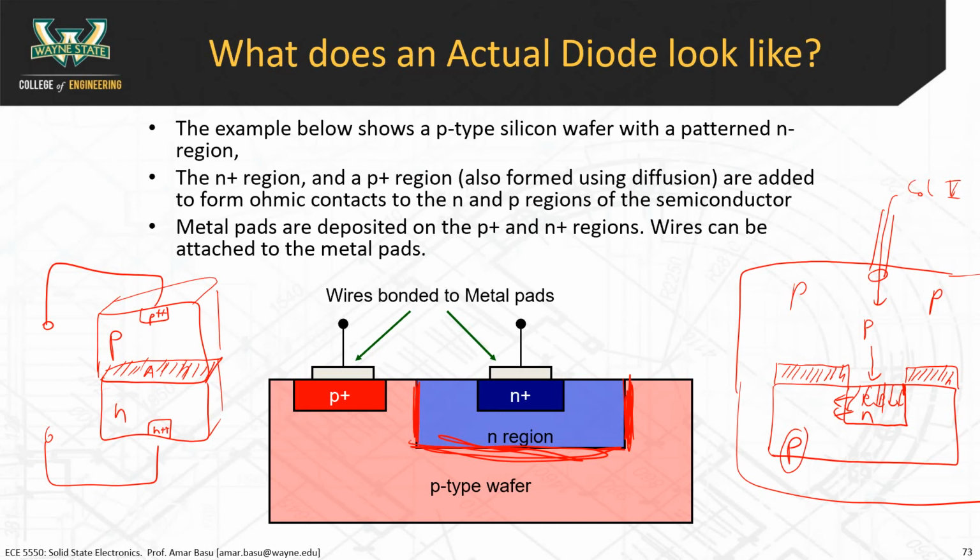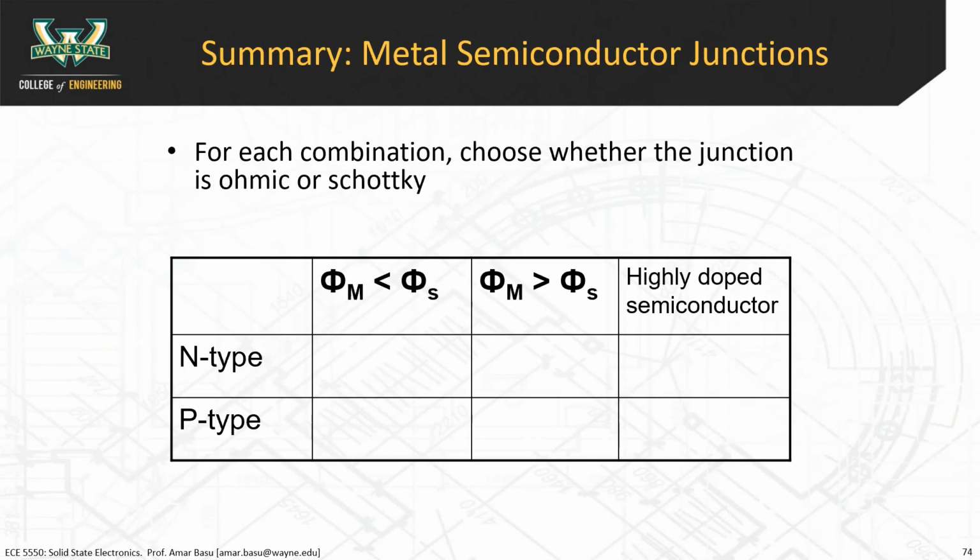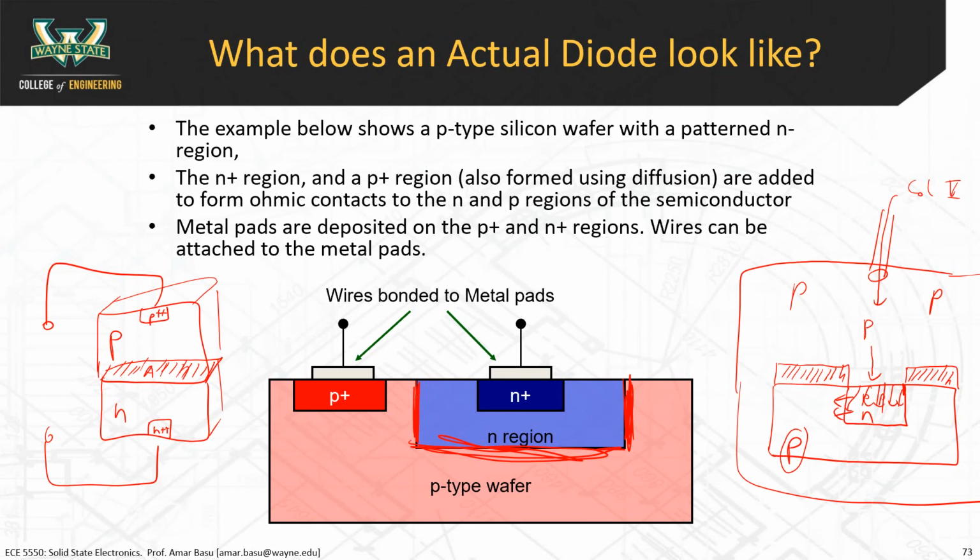Okay. Is the depletion width uniform around the entire interface, all 5 sides? It should be. Yeah, it should be. So if the doping's the same and the voltage potentials are the same everywhere, then yeah, you form a depletion region on all 5 sides. So yeah, you got it.